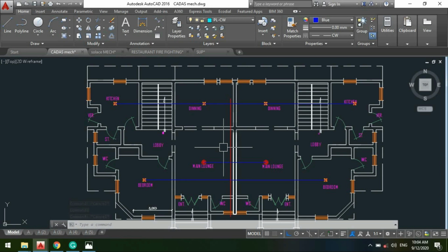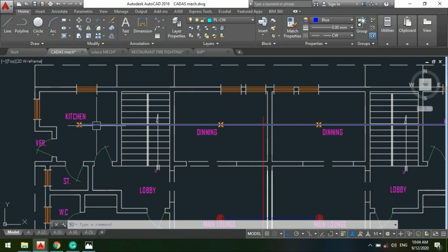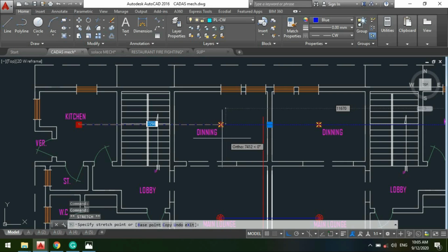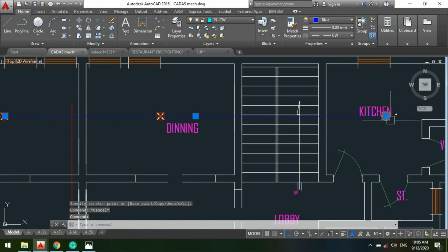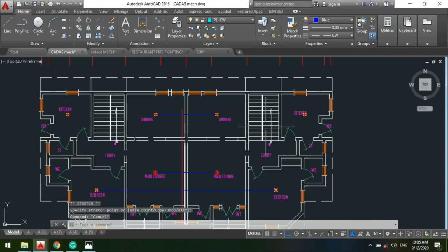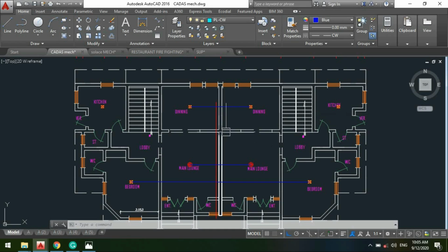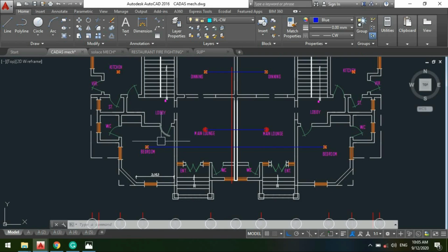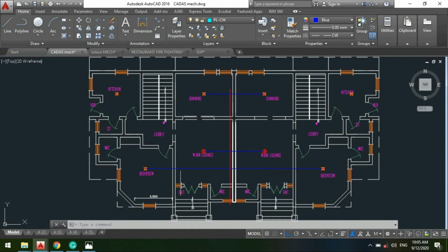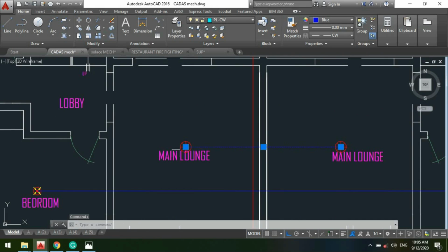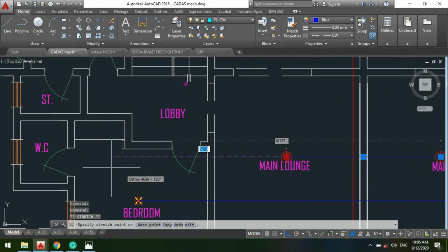So we are now required to use our technicalities. It's obvious that you can't connect your distribution pipes through this staircase here, which implies this our connection doesn't work. So let's assume it works to this extent. So it will definitely not work here too. The question now is, how do we connect this kitchen sprinkler to the cross main? Likewise, how do we connect to have a minimal number of fittings? To achieve that, let's assume we have a simple connection here coming here, or probably this connection extends like this.